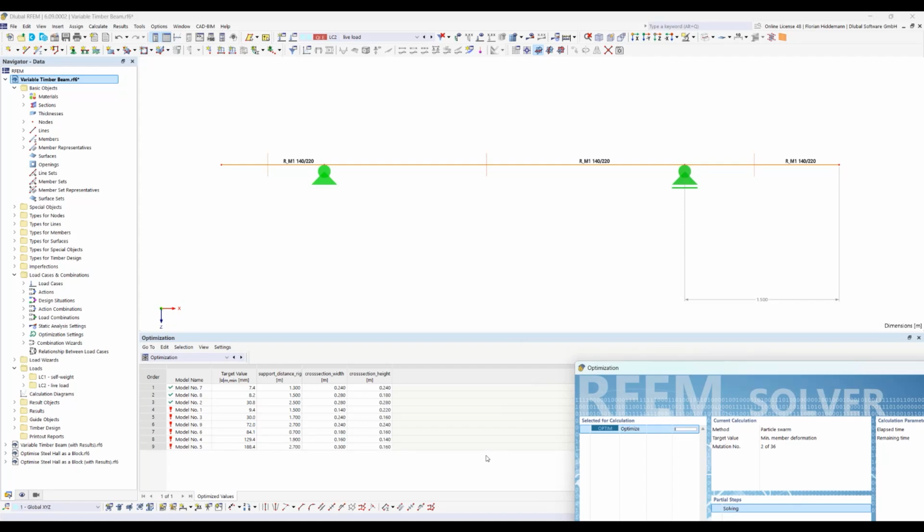This is a small little feature, but very useful if you have already spent some time with your model and calculated it, because now the optimization add-on checks each new mutation. And before it calculates it, it looks up into the result table and sees if this mutation was already calculated upfront. If this is the case, we jump automatically to the next mutation without calculating it. And if the model mutation is a new one, which is not stored in the list, the add-on just calculates it and adds it, like you can see here in the background.